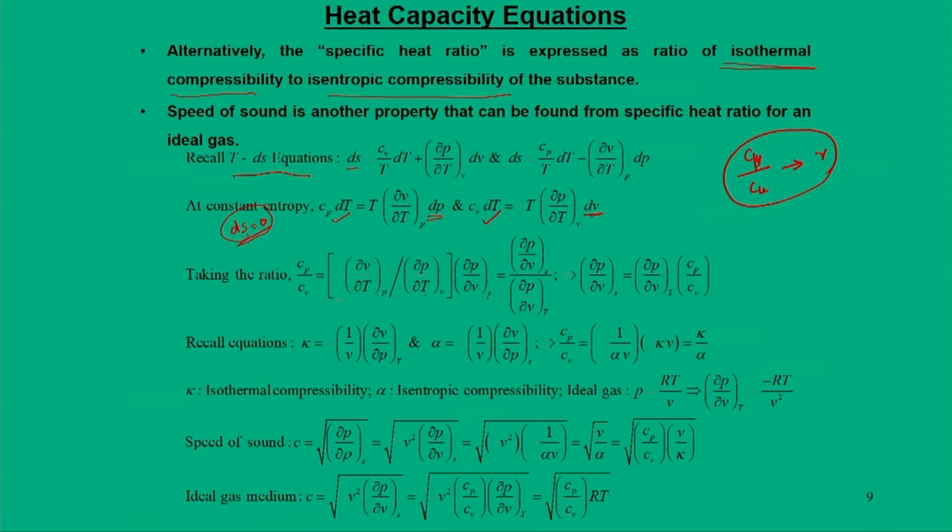Here we can see that the entire relation is between P, V, T, and it is a cyclic relation, and this term, minus dou V by dou T at constant V divided by dou P by dou T at constant V, comes to this expression because P, V, T are cyclic, so we have used the cyclic mathematical relation.